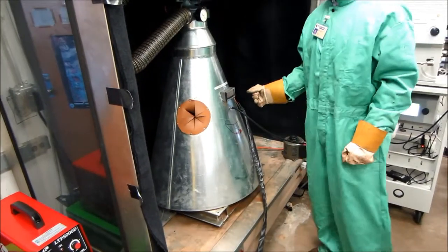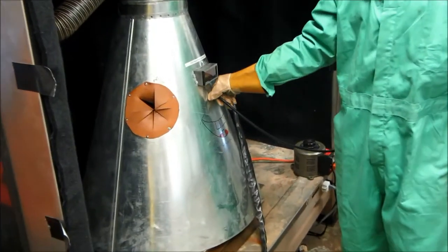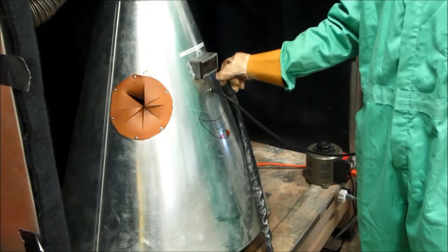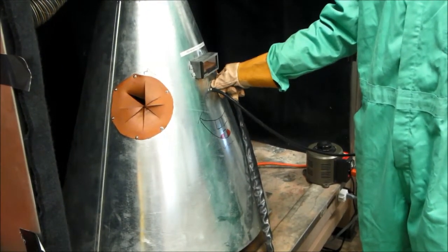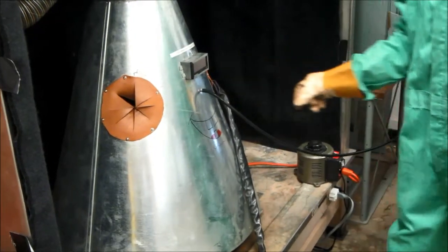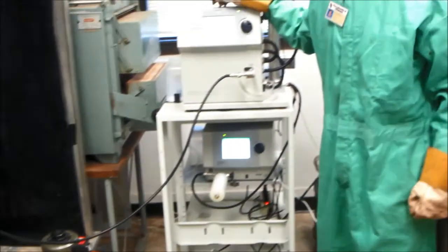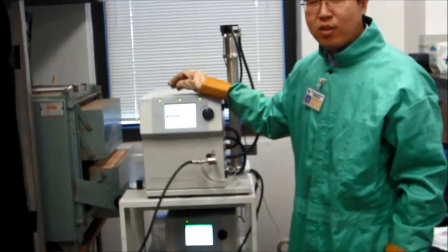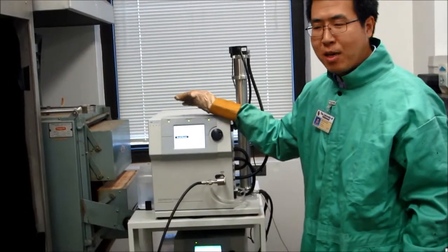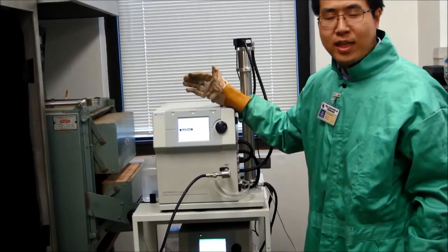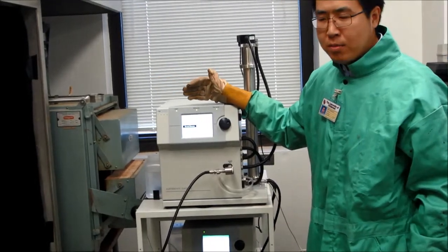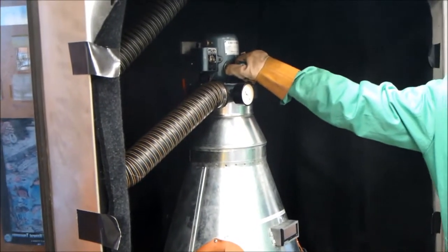The particle size measurement will be sampled through this inlet on the chamber. The location of this inlet is approximately breathing height. The aerosol samples will be delivered to the SMPS with a flow rate of 1.5 LPM. The sheath airflow of 3.0 LPM will provide a size range of 10 to 500 nanometers. Between each measurement, we're using the high volume airflow pump to purge the chamber.